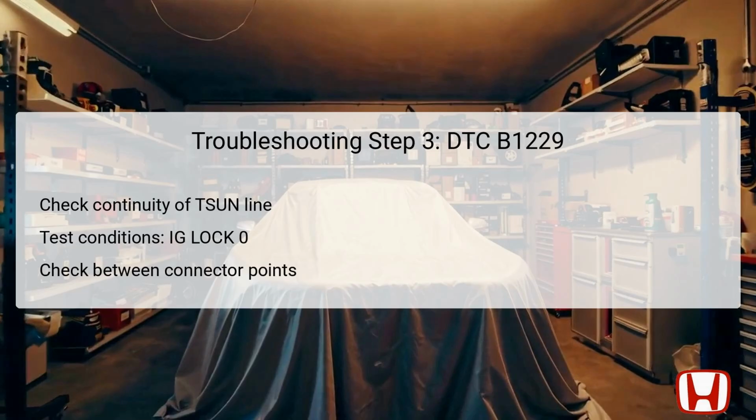At this stage, you will assess the circuit for continuity by checking between test point 1 at the climate control unit, 32P connector number 21, PUR wire, and test point 2 at the sunlight sensor, 5P connector number 2, PUR wire. Continuity indicates that the T-sun wire is intact and functional.